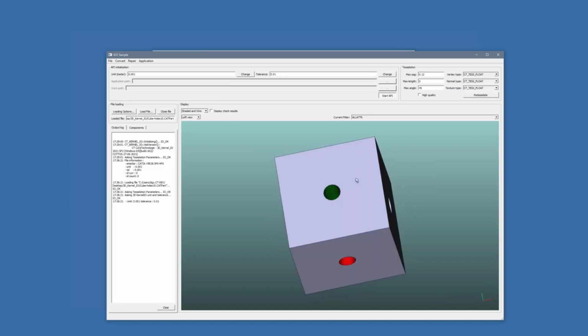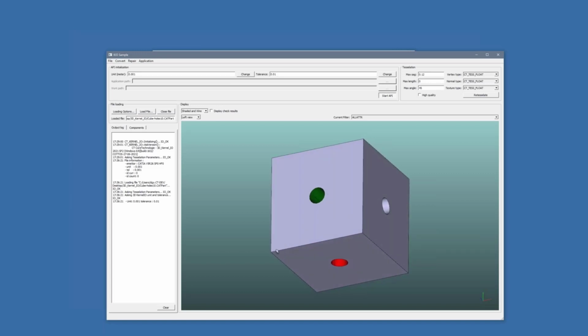That means they contain plane definitions, cylinder definitions, sphere, cone, torus, etc. And they also contain some trimming curves, because all such kinds of surfaces like plane, cylinder, sphere, cone, etc. are infinite in the geometry. And so we have to trim them with trimming curves, which are the black lines you can see here.